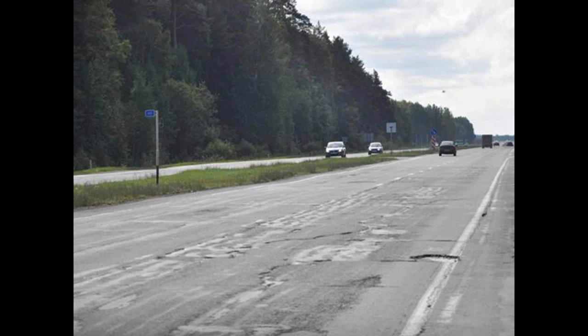So I think we can all agree nobody likes a bad surface. The number of problems that we can get by creating surfaces in Creo is we can see poorly merged entities. We can see tangency that is lacking, curvature continuous problems. You know, if we're working with a C2 curve or a G2 surface, how do we actually make sure that that curvature is actually a curvature continuous spline? How do we make sure that we can even turn this surface that we've created into solid geometry?